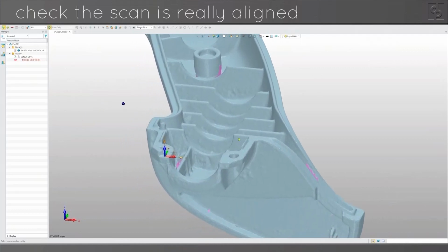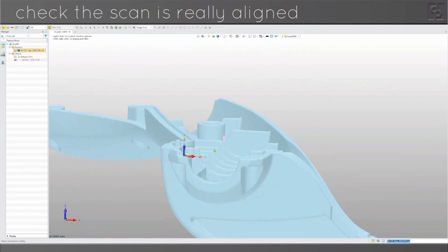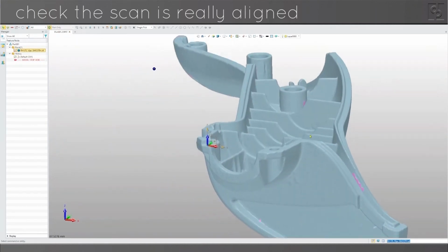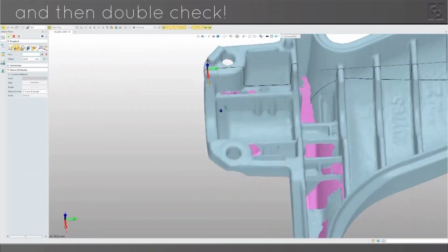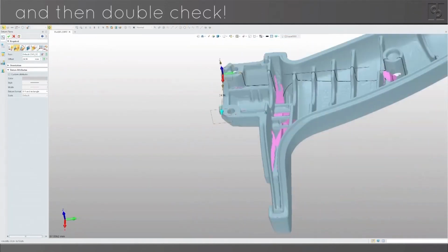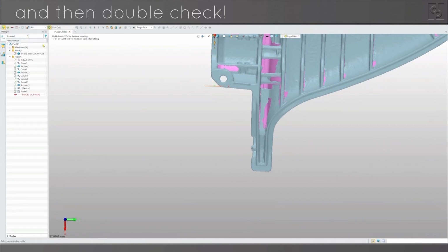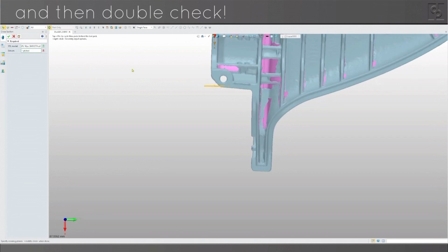Now there's a bend here in the part. We're not going to use that for the planar reference, so everything's going to be concentrated down this bottom end. I'm still checking that position, and I'm doing it by creating a plane offset from the construction axis, and then I'm going to create a section through that plane and analyze the section.